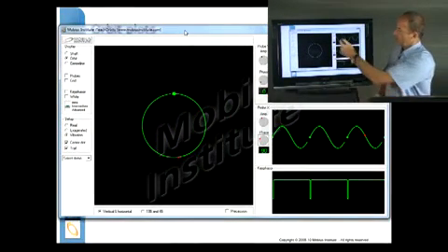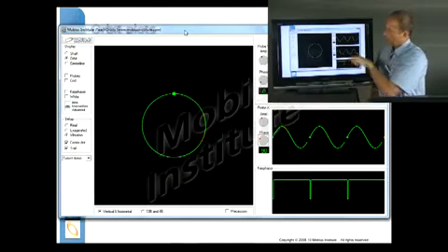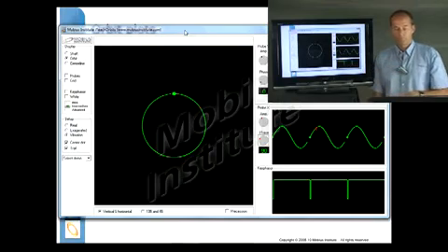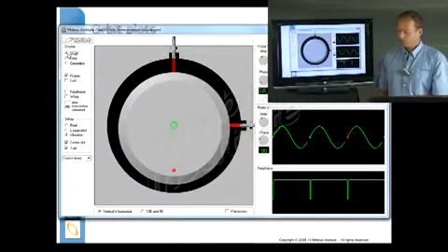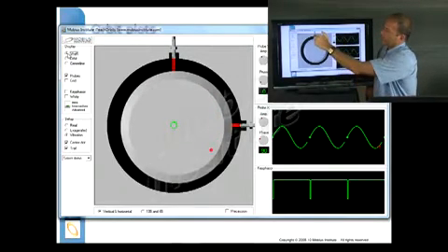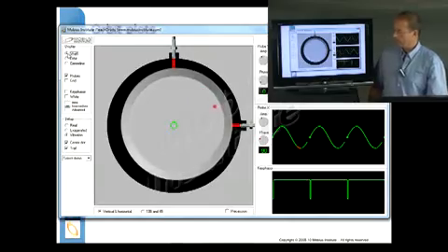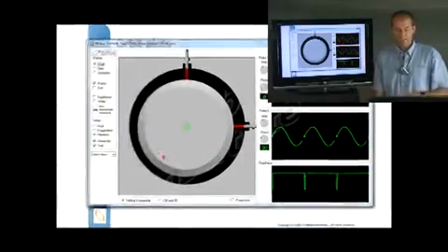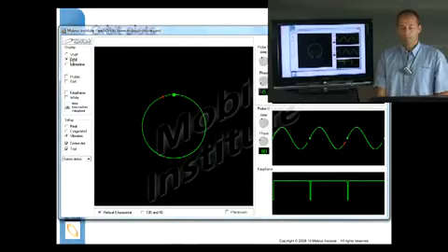So there's the voltage from my Y probe, which was up on top, voltage from my X probe, and I've also got my Keyphasor, a once per revolution signal, going there. So again, if I show you the shaft, there it is spinning, and this is rising and falling according to the gap there, and this one's rising and falling according to the gap there. When I plot those against each other, I end up with an orbit plot.